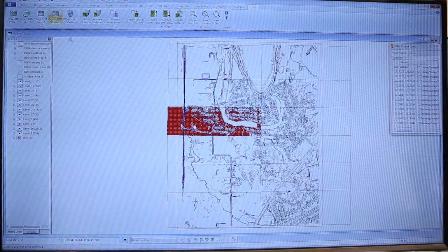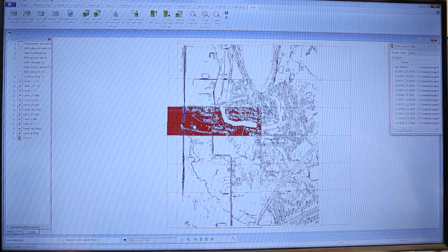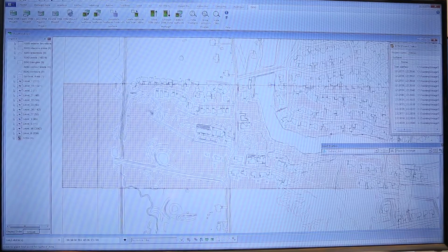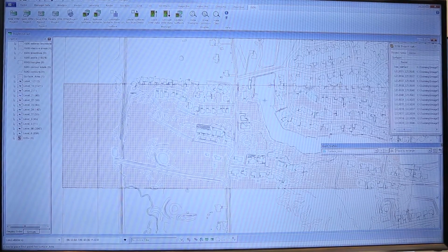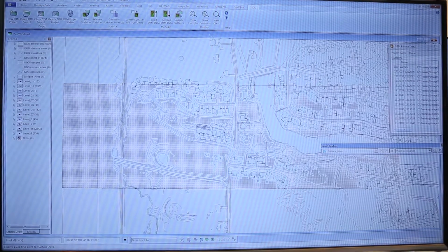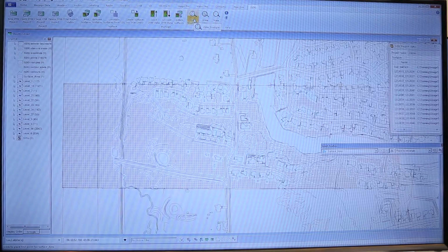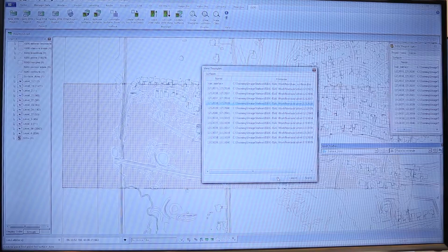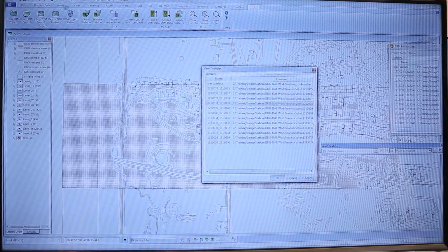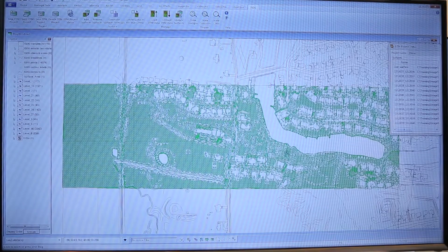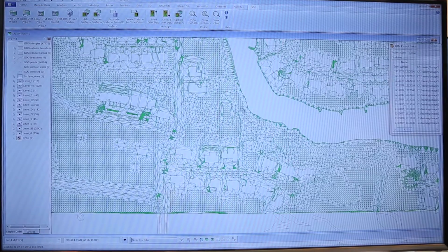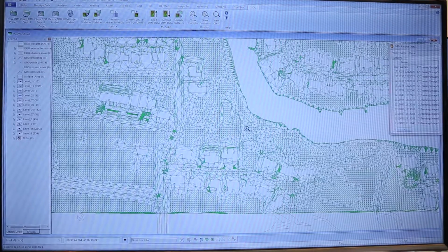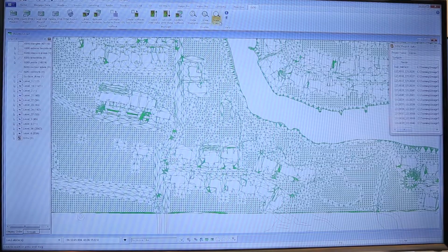So these are the points which were just created from the automatic elevation processing. And you can then go into the stereo environment to review and edit those. So in the ImageStation DTM for GeoMedia, we can view the triangles as another way to check the results. So these are the triangles that would be written out once we're finished to be used for orthorectification.